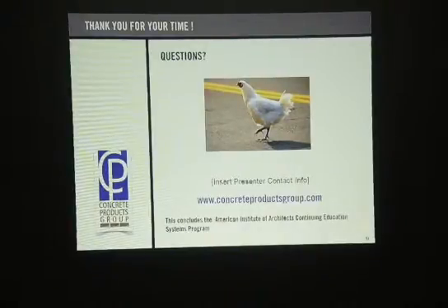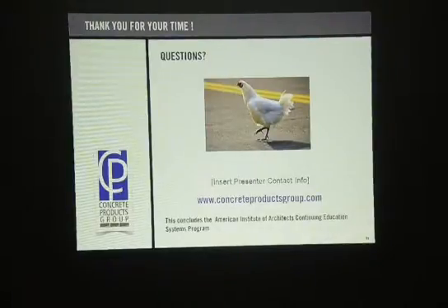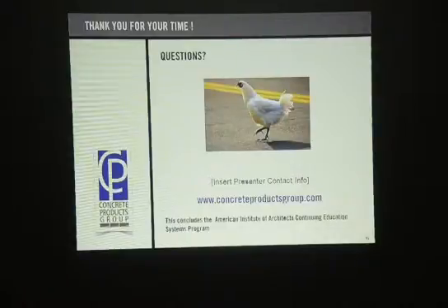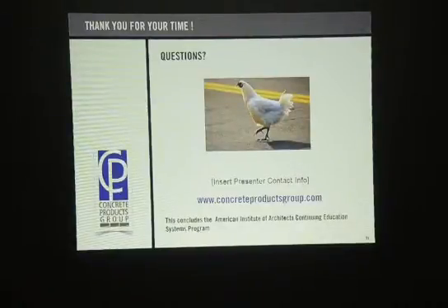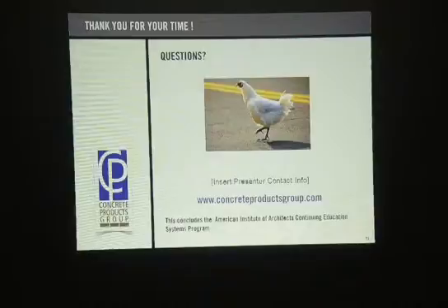As far as the pavers back there, some people want bevel pavers because they look really nice, and you're going to basically fill the seams with sand, okay? Most people put pavers over compressed dirt that has rock and aggregate on it to basically make it stable, so we don't have to worry, hopefully, about sinkholes. But the real advantage of pavers, in my mind, for both pedestrian pavers and vehicle area pavers, is the fact that they are permeable.